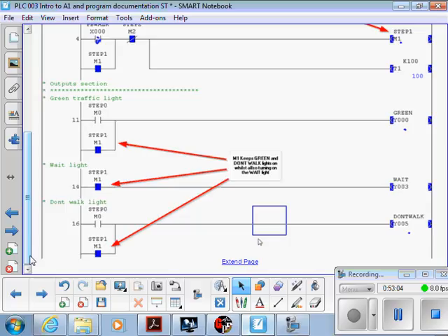The specification says the amber light flashes on returning from stop through to green again. I'd leave the flashing bit right till the end. Get everything else working first, red, amber, green, green, amber, red, and then worry about making it flash. You might want to use your little circuit that you had a go at the other week, where you create a flashing light, 1 second on, 1 second off, to do that. Alright? So I'm not going to go any further than that.